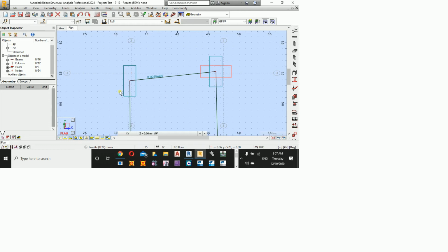So once again, if you are going from Revit to Robot, or from Revit to any other software, it will always link you center to center only. So it's better to modify the columns in terms of positioning inside and outside in Robot. In orientation, it's easier in Revit. But it depends on how you work.